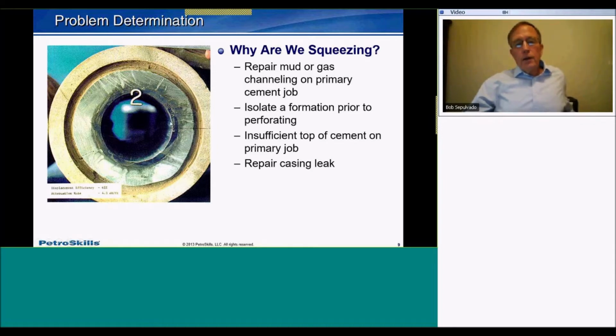Now, one thing you need to know about a cement slurry, it is intrinsically lazy. A cement slurry is going to seek the path of least resistance, and it's not going to work any harder than it needs to. So in this case, the casing was placed concentrically in the simulated formation, and then the well, as is done in operations, the mud is circulated around, and then the cement is put in place. So the water-based mud that is close to the formation and has higher leak off tends to become less mobile, a higher solids to water ratio, whereas the mud that is closer to the casing tends to be more mobile.